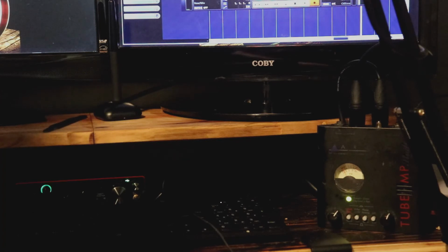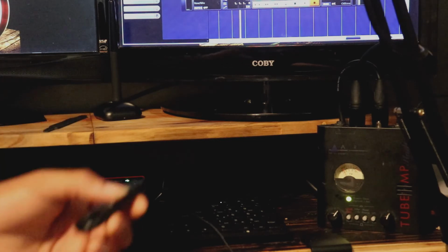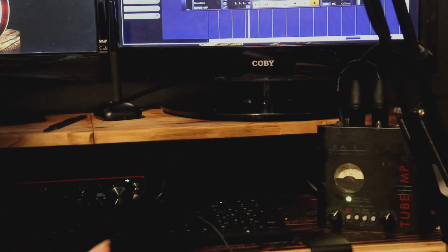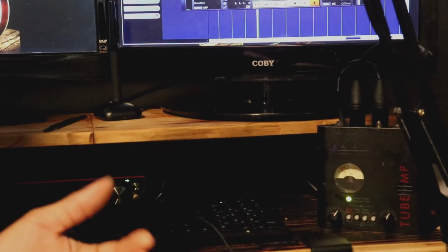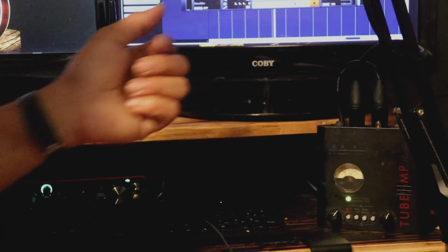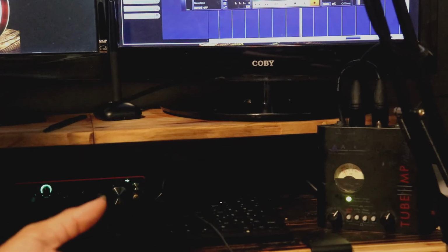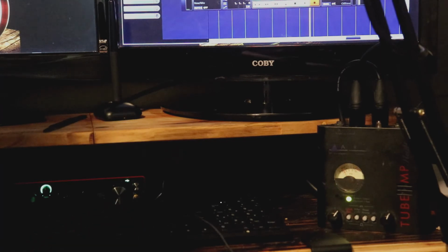Now, op amps are good at supplying gain. They're really good at taking really small signals and supplying gain in discrete electronics. But again, what we're doing here is a little overboard for your typical op amp setup, because the voltage that I'm going to have coming out of this preamp is so high. So the next logical step would be to use a tube. Use a 12AX7, because that would be able to withstand the voltages that I need, and then some.